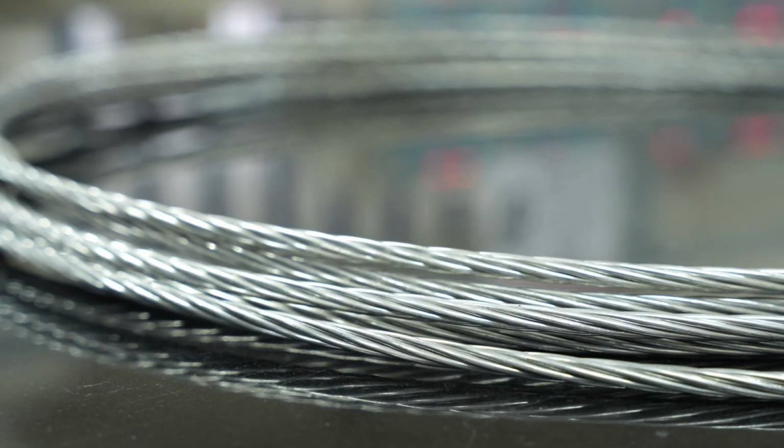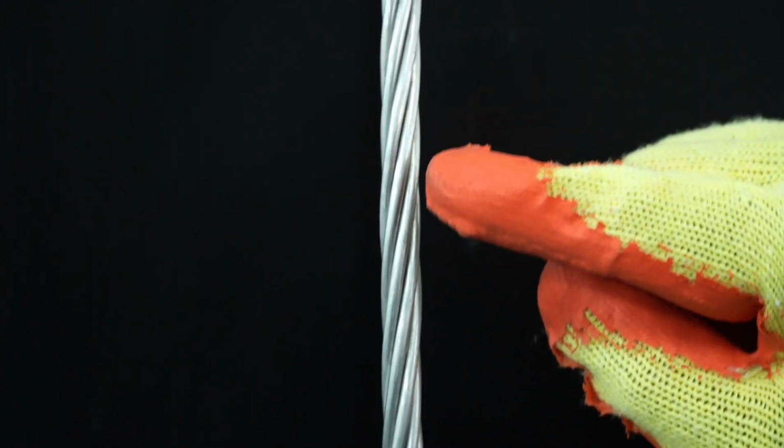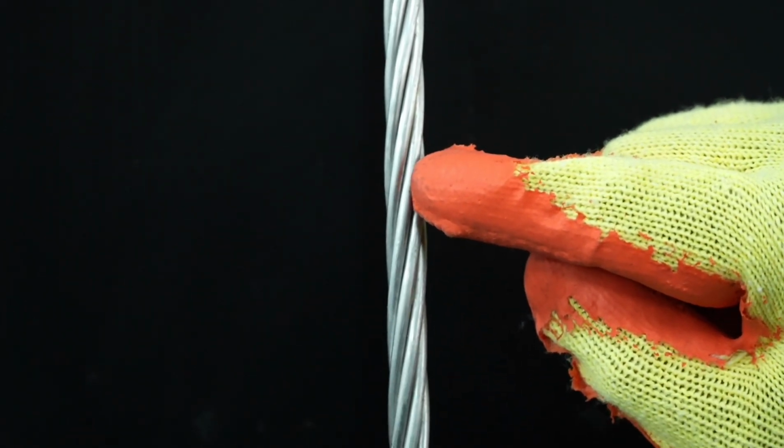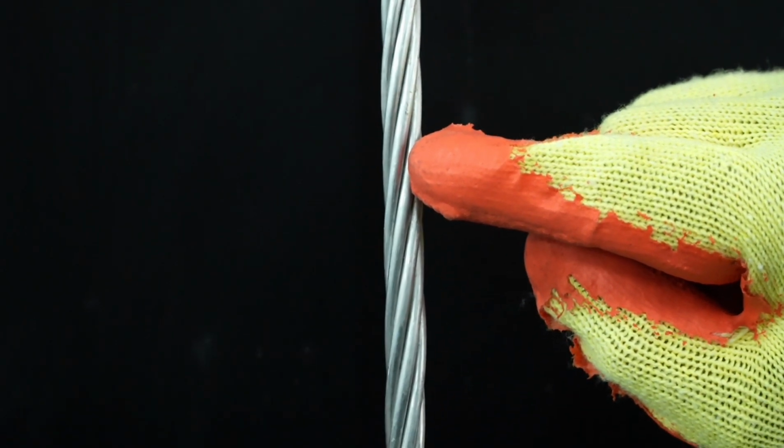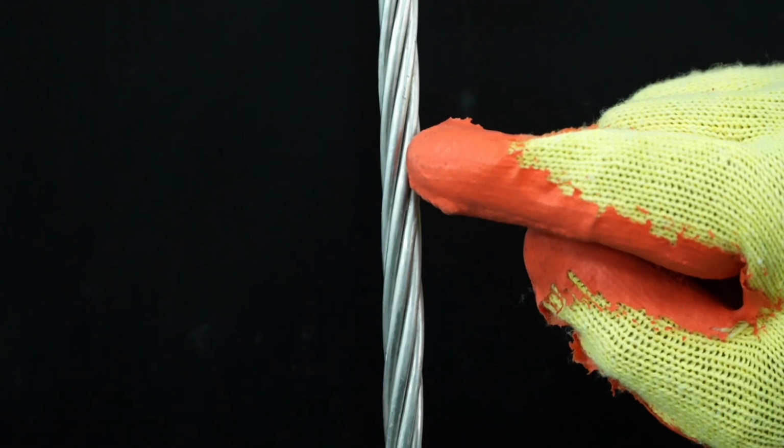Procedure: the wires used in the construction of a stranded conductor should be evenly and closely stranded. The direction of lay of strands can be either right-handed or left-handed. With right-handed lay, the wire shall conform to the direction of central part of letter Z. With left-handed lay, the wires shall conform to the direction of central part of letter S. In both the cases, the conductor should be held vertically.